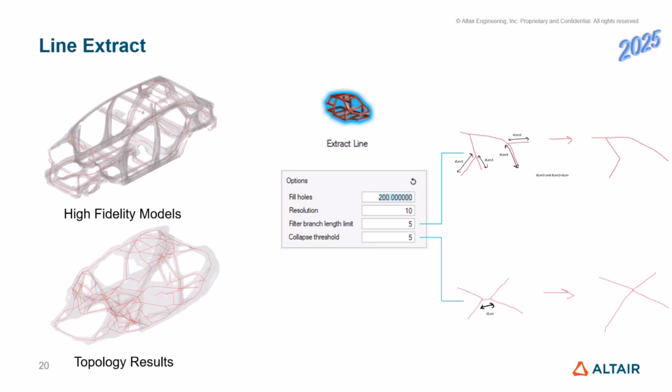Okay, so you can go from a 3D topology result or even 2D, extract the midline, and then whether that's a 1D representation or you're creating ribs or whatever it might be, it's a pretty powerful interpretation tool. There are a couple of options. So we automatically fill and patch the holes, in this case in the upper left-hand side. Otherwise, the algorithm will actually bleed out. So you'll need to make sure it's vaguely watertight.